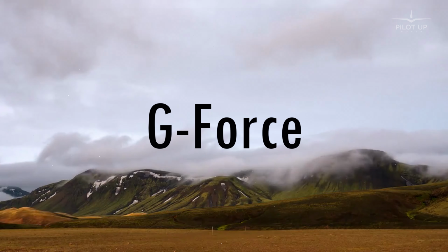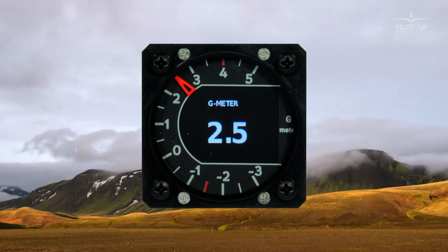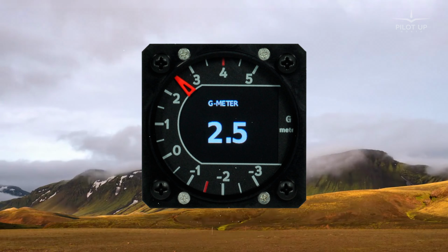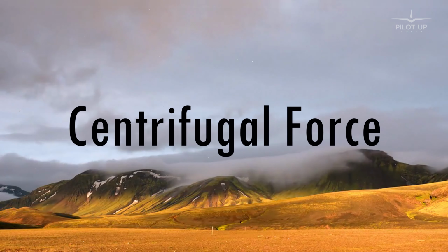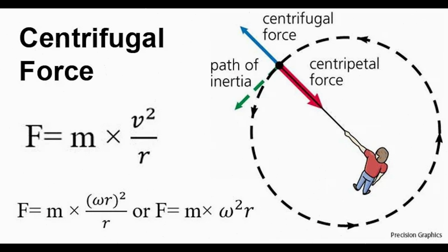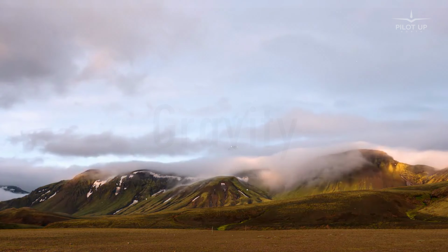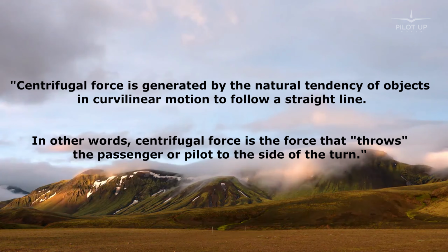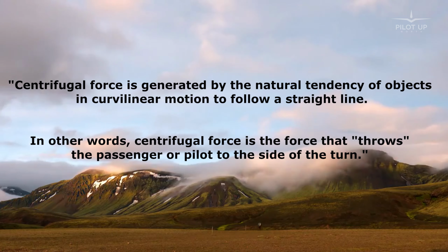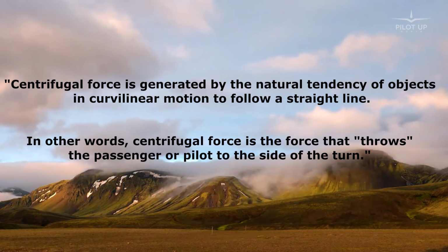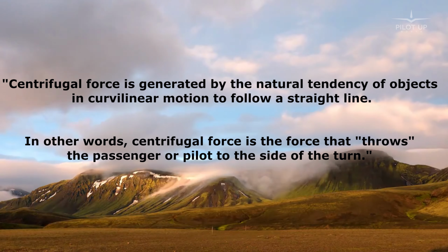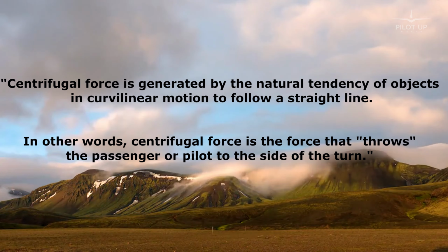G-force. During a turn, the G-force increases because the aircraft is being subjected to two forces, centrifugal force and gravity. The centrifugal force is the one acting to push the aircraft out of the turn, and the force of gravity pulling the aircraft down. Centrifugal force is generated by the natural tendency of objects in curvilinear motion to follow a straight line. In other words, centrifugal force is the force that throws the passenger or pilot to the side of the turn.